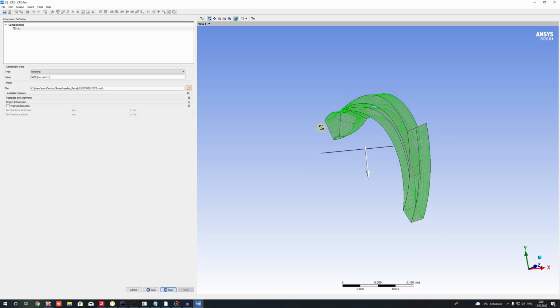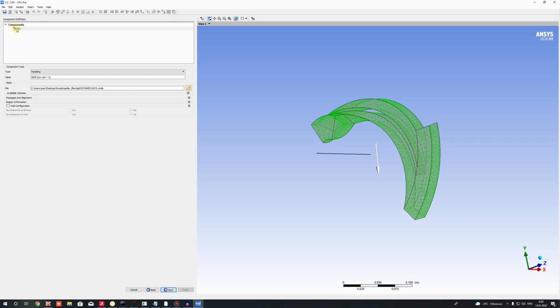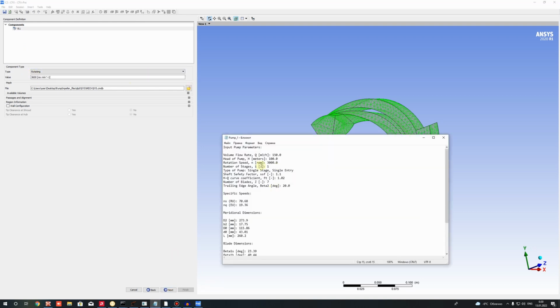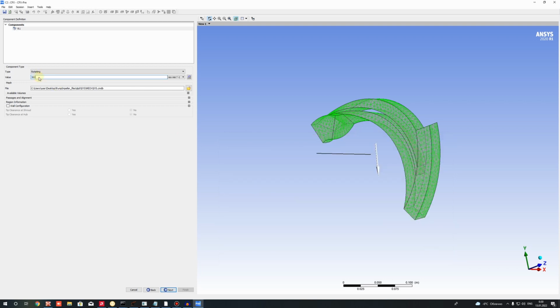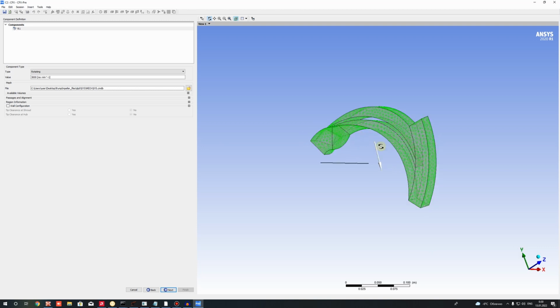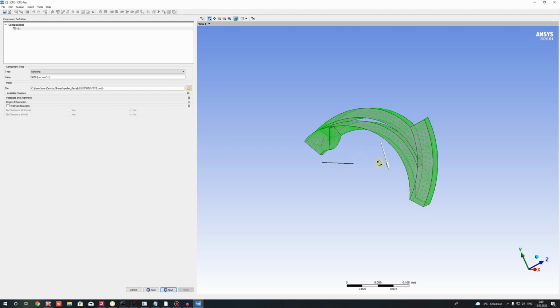We have the steady state, axis visibility, set it, and here we have the one domain, component as it's called in CFX, rotor 1, and let's set the rotation per minute. In previous video tutorial we set the rotation speed 3000 RPM. Let's set it here, and as you can see on the screen, you have this arrow, and we have the counter rotation.